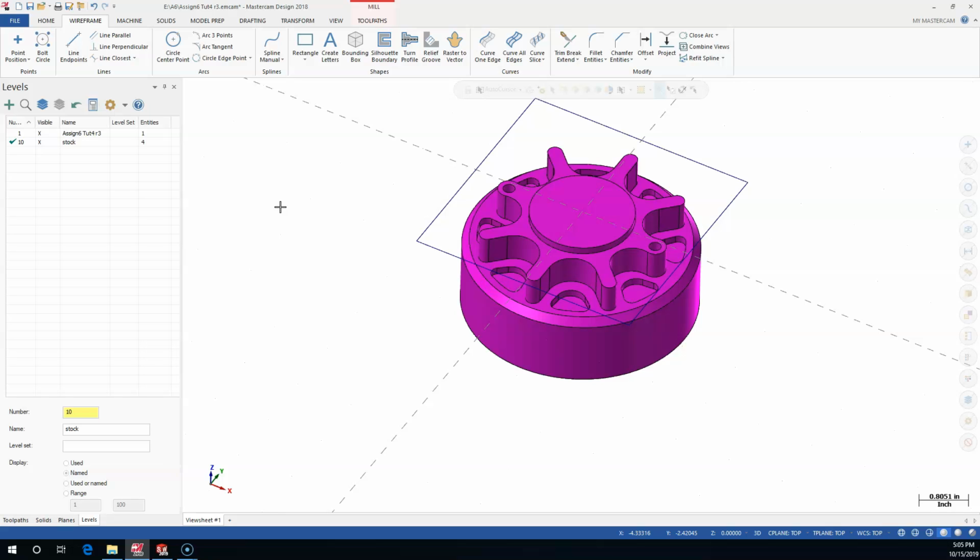I picked stock that's 2 inches, so that would be a good reason not to get too aggressive on our cuts. Holding on to 1/8 of an inch of material, going into acrylic, so it'll look nice. We're not going to experience a lot of loads unless we just out and out melt that acrylic. If we are running in aluminum, then I have to be a little bit more concerned with it.